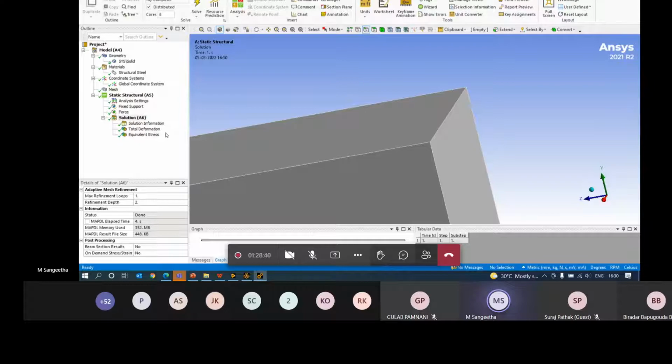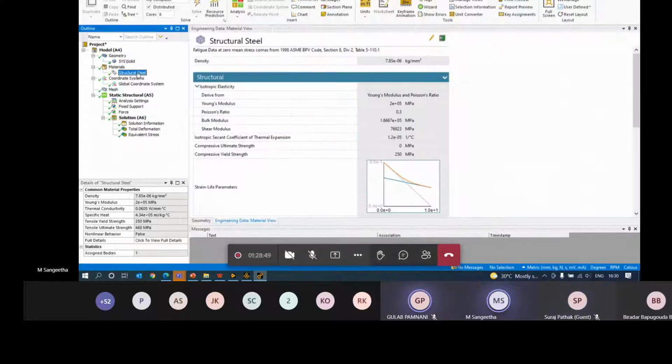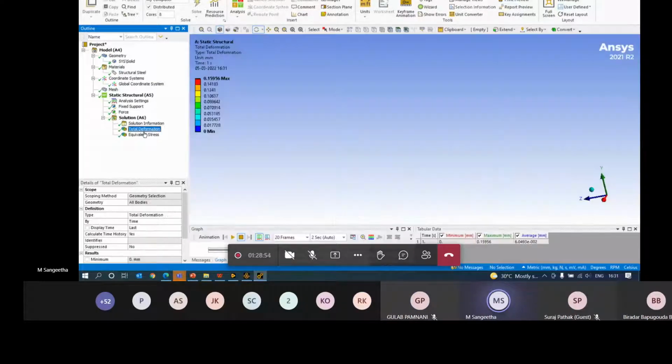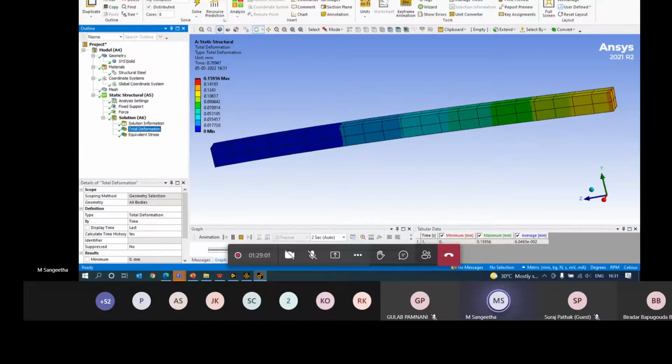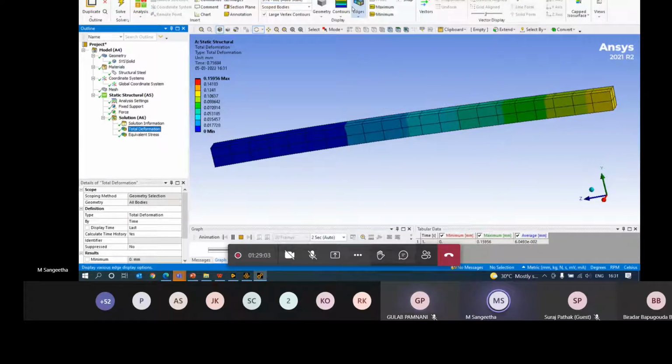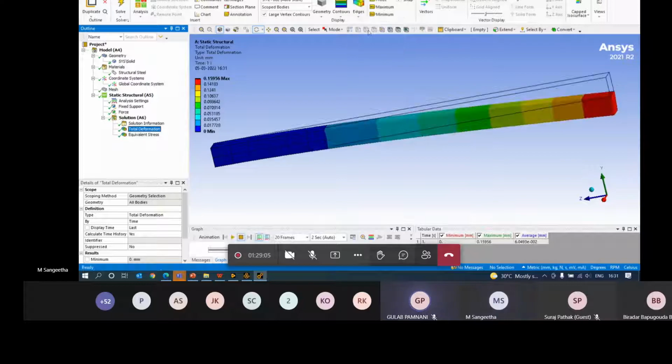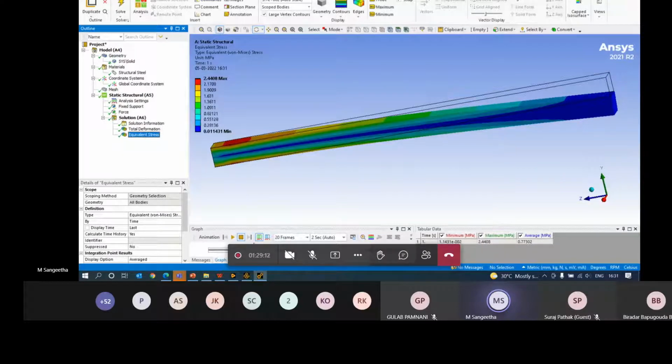When you move on to more than a single component, you also have to work on the connection part, and since we used the default material, you need to work on defining a material as well. You can click on this and see the results. You can see the actual deformation, how it takes place, and where stress is generated.